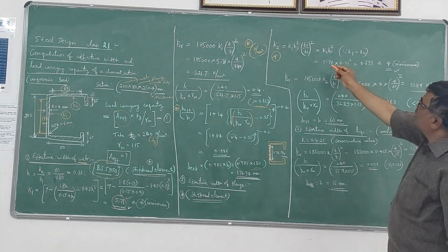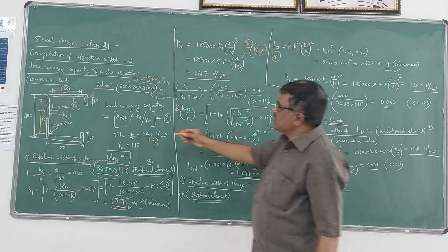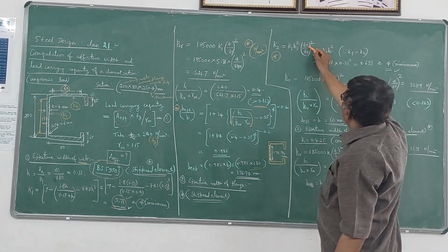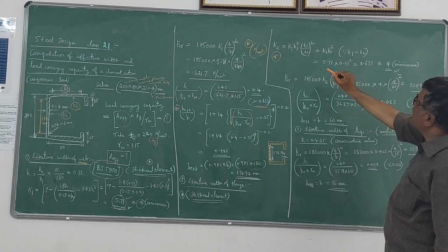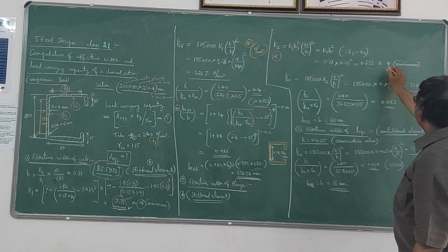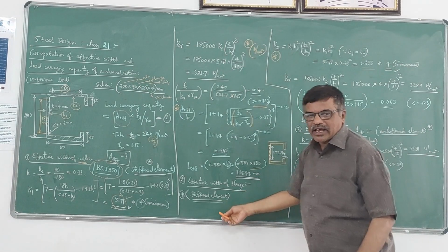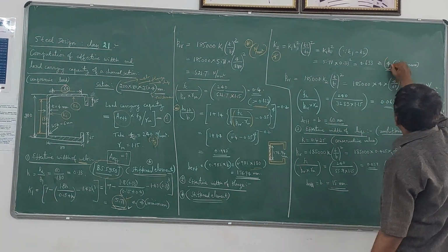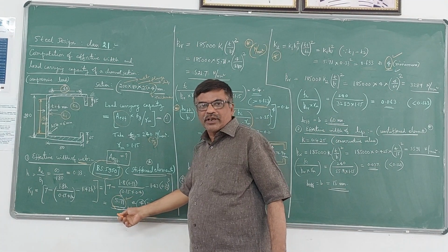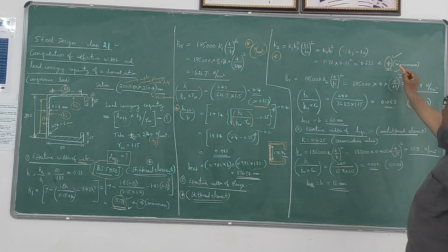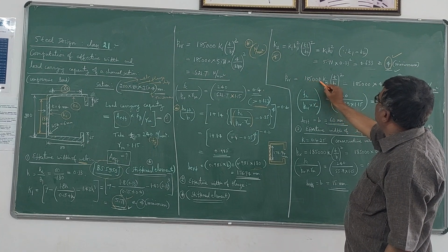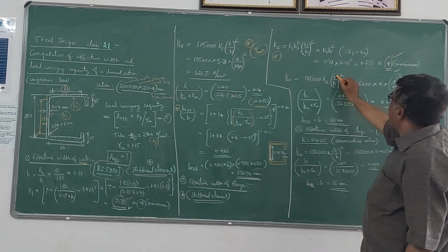So this is the formula. Here of course T1 and T2 are the thicknesses of the web and flange. Both are equal to 4 mm, so it becomes 1 here. If you simplify by substituting the K1 value and h value, you are going to get 0.633. But once again, 4 is the minimum because it is a stiffened element. So we have to take this 4, because 4 should be the minimum. Here 5.71 is greater than 4, therefore you have to take the greater value. Here the greater value is 4, so this value we have to take for K2. So PCR once again is given by 185000, and instead of K1, K2 will come here, T by B whole square.